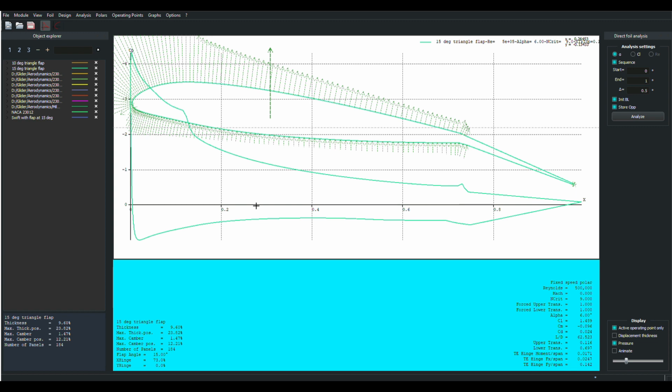In other words, the way you can think of this, if I came in with a razor blade and lopped off part of my current trailing edge up to where we see that pressure reversal occur, that would give me enough thickness on the elevon, a lot like my original wing, where I have enough thickness there where I can put in some structure and keep it from being too floppy.